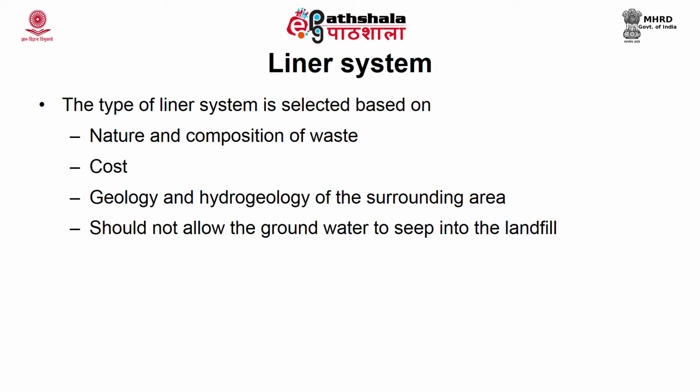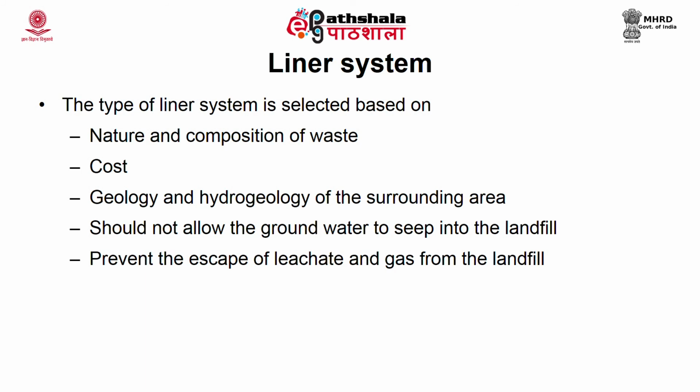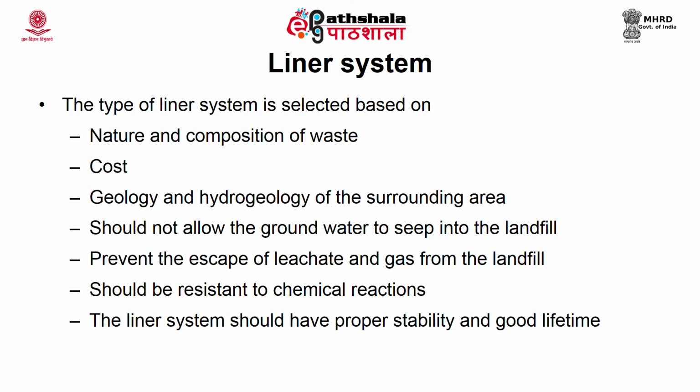I hope you understand, because if the water table increases during rainfall, obviously the groundwater will enter. When the groundwater seeps into the landfill, it will create more leachate generation. So, you have to be clear that the liner system should protect your landfill from groundwater entering. Then it should prevent the escape of leachate and gas from the landfill. Also, it should be resistant to chemical reactions.